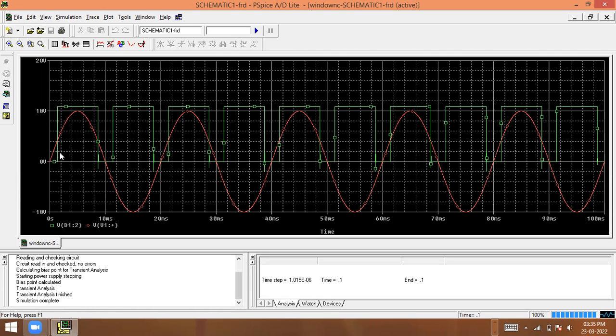Okay, so this is the exact output. Now see here, this is 0 to 4. I have given 4 as a UTP, right? So at this point, till here, the output is low. Whenever it reaches the point, that is 4 volt, it goes from low to high, and it will remain high until 4. Below that, here see this waveform, here it is 4, again it's coming 3, 2, at this point from high to low we are getting here, and it will remain low till this point, and again once it reaches -4, again it's going low to high, and it will remain high till -4.